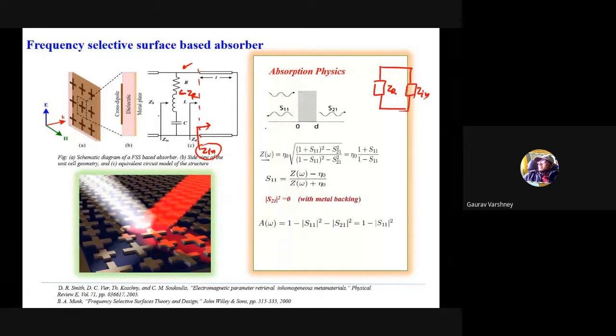And finally, this is the characteristic impedance of free space, which can be represented by Z, and the total input impedance you can calculate in parallel: ZR parallel to Zin gives Zin total. So this will be the total input impedance offered by this full absorbing unit cell. And in a further way, this must be matched to eta naught because the S21 and S11 parameters are 0.